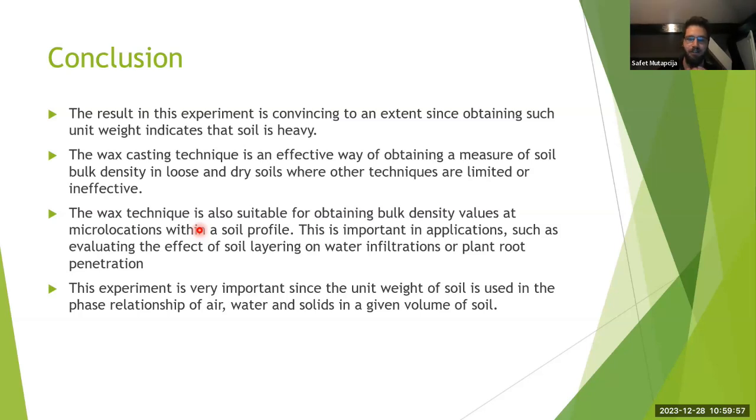Then you're going to send all those samples to the laboratory with the help of a geotechnical engineer, and someone is going to determine the mechanical and physical properties of the soil. Based on the log of your borehole, in the report they're going to tell you what kind of foundation you need for your building, where to put foundations, what the mechanical properties are, and what the settlement of your foundation will be.